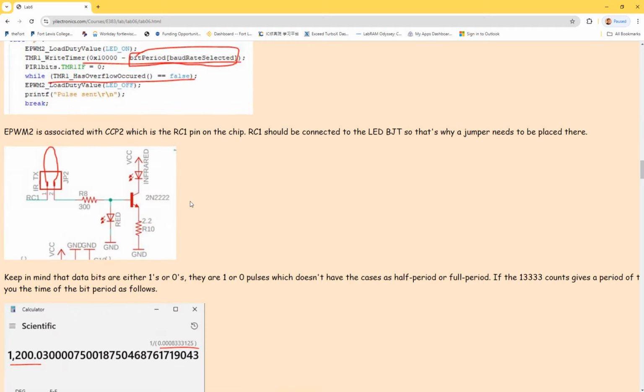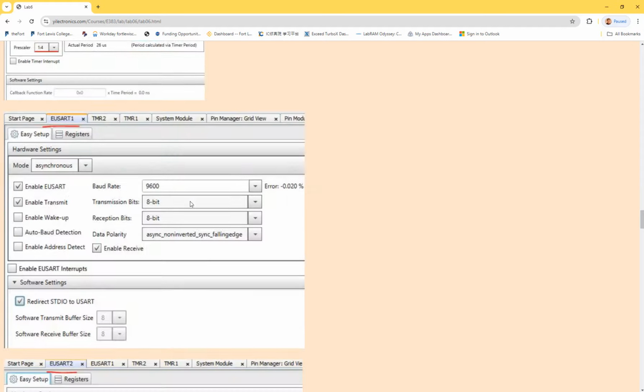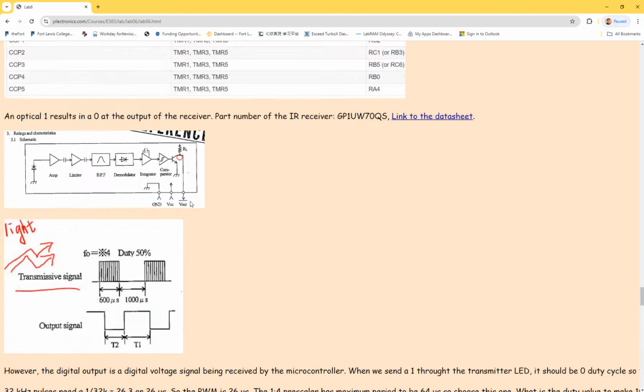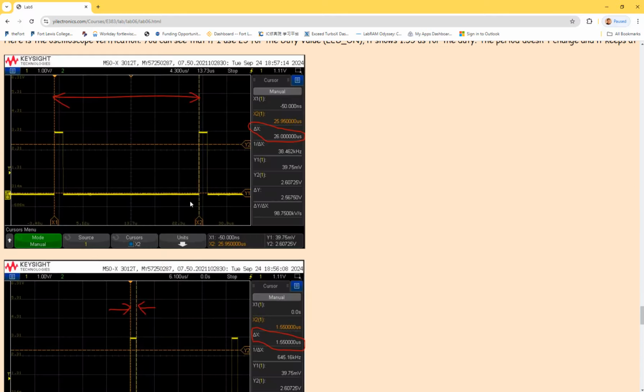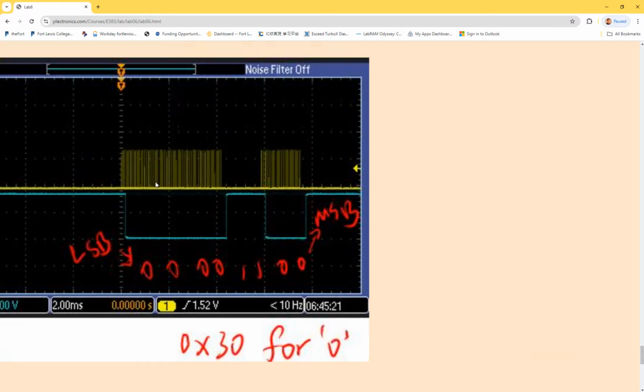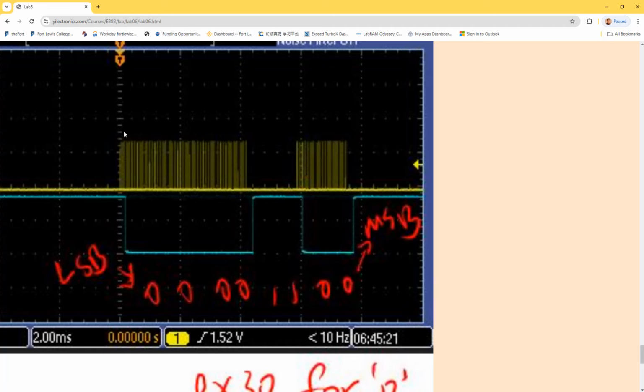Let me show you. Pulses give a 0, depending on the decoder type. So this decoder on the board is going to give you a 0 if you see a series of pulses. Pulses give you zeros, and zeros give you 1. Doesn't matter, you can modify the decoder however you want.